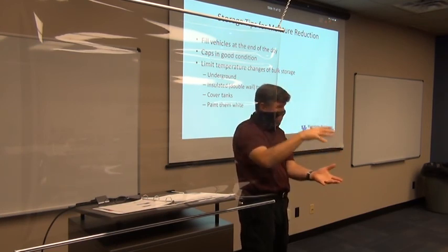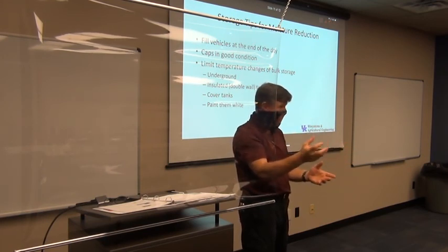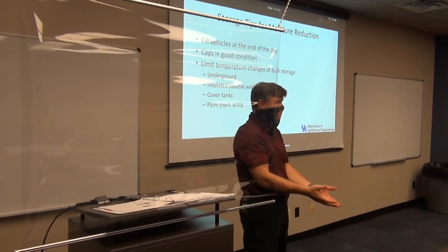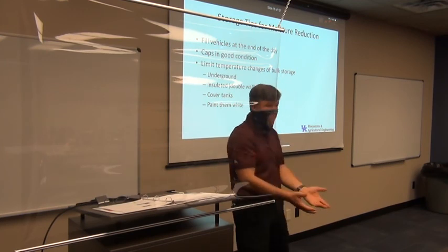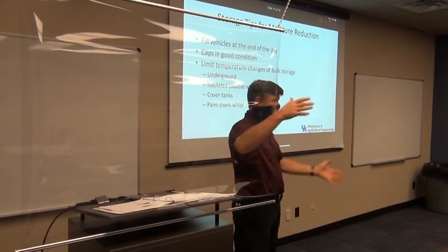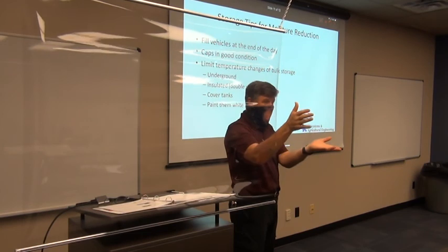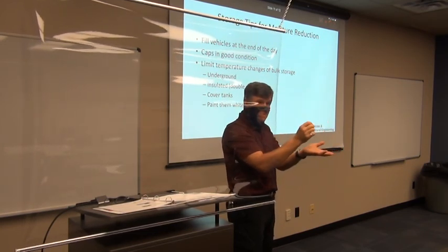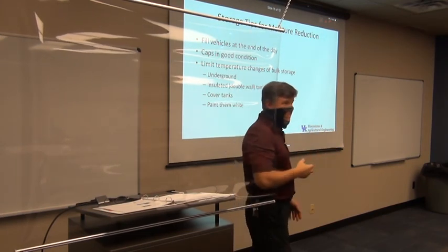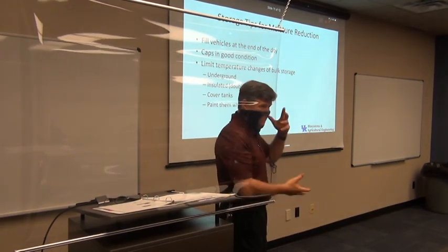So I'm going to pull cool air into that tank as it cools off. That cool air is going to have a lot of moisture in it, and then when it gets cool, it's going to have a tendency to condense on the inside of the tank, and now I've got water in my tank, which I don't want, all right? So why does filling it up help? If I fill it up while it's hot at the end of the day, what's that do for me? Do I have all that big empty airspace in there sucking in? No, so I have very little airspace, so even if it does suck a little bit in, there's not going to be much moisture that's going to come in, as opposed to what would come into a large tank that is breathing and pulling air into it, okay? So think about that, psychrometrics, all that stuff, put it all together, be an engineer.